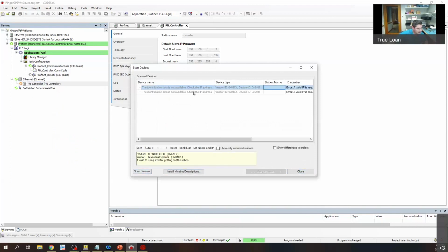They disappeared. Okay. Because it's the first time I'm setting up this Profinet network, and again, this is another Profinet nuance, you don't have to do this for the other protocols, I'll have to provision a name and assign an IP address to these devices. And it has to be within that good range that we set earlier as well. We'll start at 2, and then this one will be 3. 192.168.1.3. Okay.